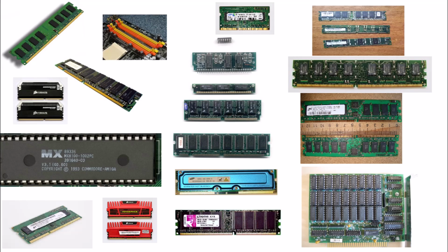EEPROM memories, Electrically Erasable Programmable ROM. Each byte can be electrically erased and the new contents written directly to the device in which the memory normally operates, and one write cycle is sufficient to program any byte. Taking advantage of this capability makes this memory ideal for running new software or modifying the contents of existing memory. It is assumed that EEPROM memory should withstand 100,000 reprogrammings.